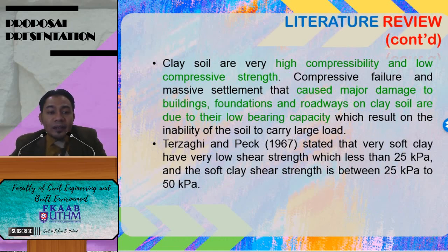Clay soils have very high compressibility and low compressive strength, and then compressive failure and massive settlement cause major damage to building, foundation, roadway on the clay soil, due to their low bearing capacity. Okay, according to Terzaghi and Peck 1967, very soft clay has very low shear strength, which is less than 25 kPa for the very soft clay, and then for the soft clay between 25 to 50 kPa. This is the shear strength of the very soft and soft clay.